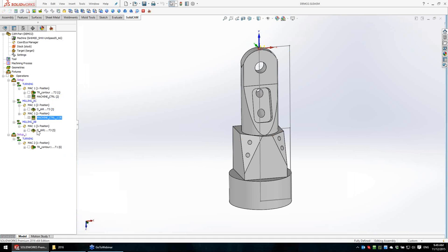The next operation is again drilling on this face, but I select another kinematic. I select kinematic milling with A and B. When I work with A and B, now I have to control axis C, which remains uncontrolled by the operation. So here in this MCO, I will send the C-axis to reference position, 0 degrees.